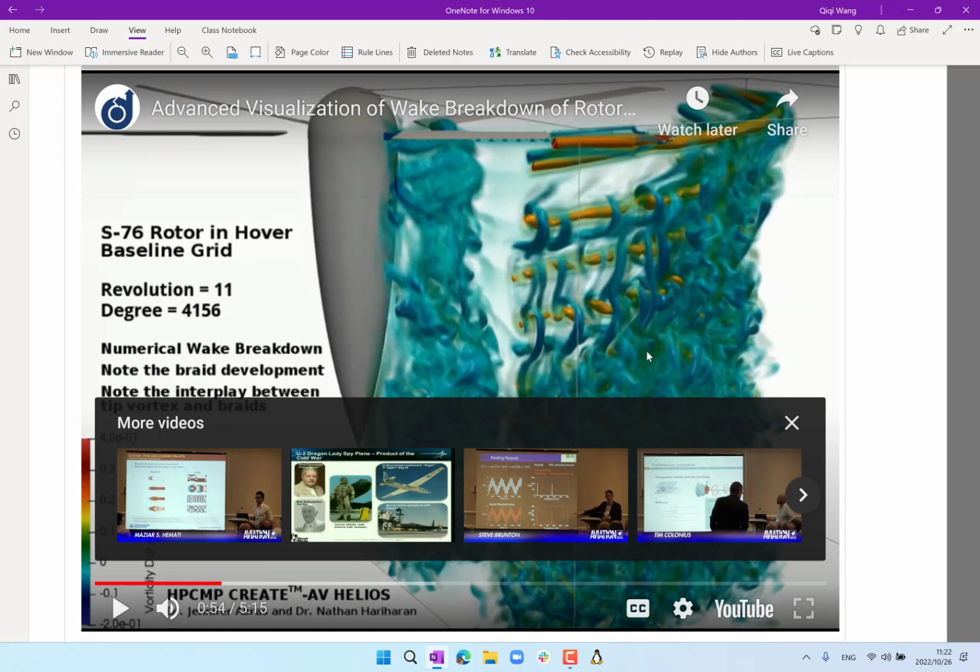What is the induced flow like in the tip section when I have a preceding tip vortex? Up, exactly, right? A vortex rotates that way. So it induces an upward flow at the tip and a downward flow in the inner section of the blade.